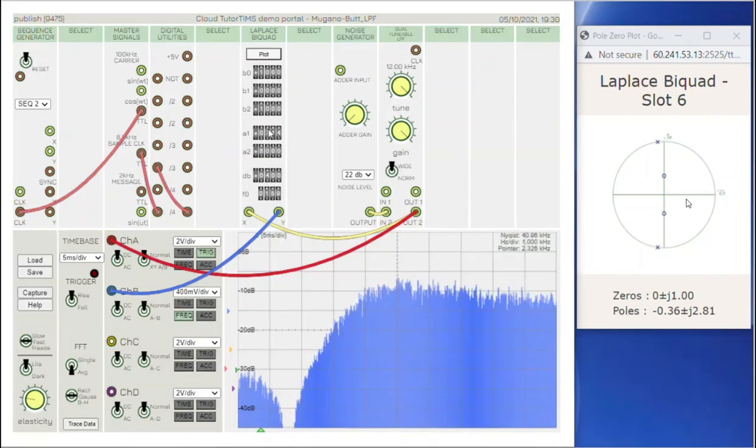If we look at the S-plane, the vertical axis, the imaginary axis, relates to the frequency of the response of the transfer function. So we'll draw that in there with this green arrow in the vertical. The equivalent on our scope display of the frequency response is the horizontal. We'll draw that in. So that's frequency, this is frequency. Let's mark 0 Hertz, DC, on the S-plane, and let's mark it on the scope.